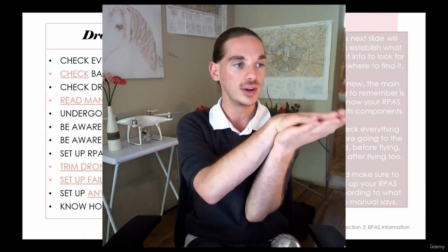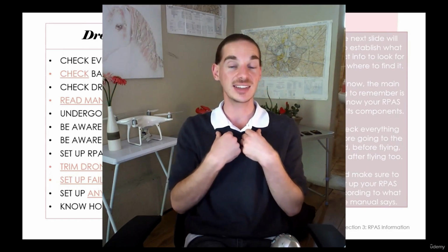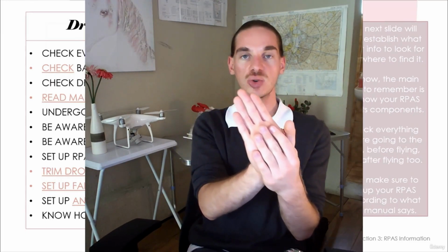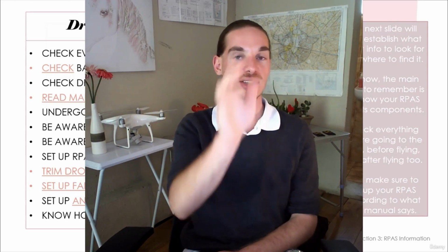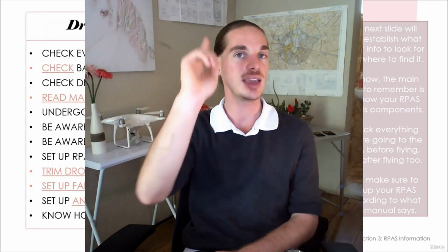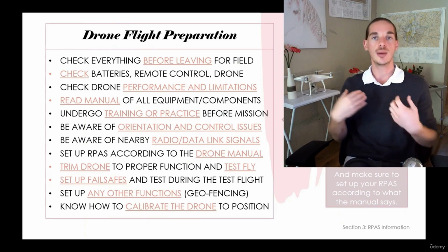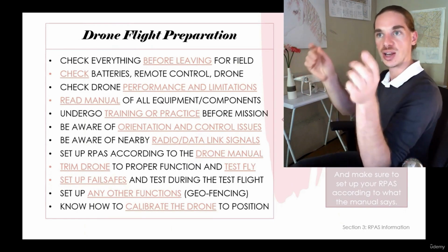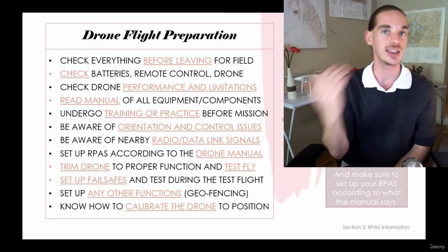When a drone is flying, its orientation changes in the air. But us standing still on the ground, our orientation doesn't change with it. If, let's say, I'm flying straight away from me, then I turn my drone to face the right of me and I fly forwards, the drone's going to go this way. It's not going to keep going forwards. So the drone's heading and orientation has changed, but mine hasn't. I'm not going to turn to match the drone. I have to stay still so that I can pay attention to everything that's around me.